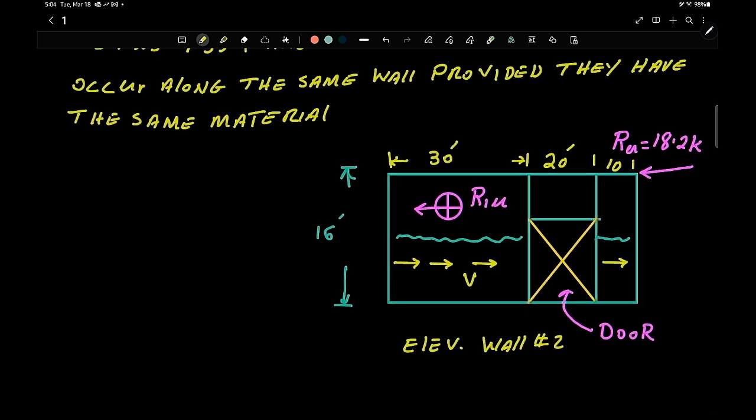Then we have the shear R_U at 180 right there, 8.2 kips, and then we have R1_U, which is the same as before, we figured it out. Then you have a shear down bottom. Of course, you have the opening where the door is, then it picks up on the other side. Let's go ahead and calculate that.